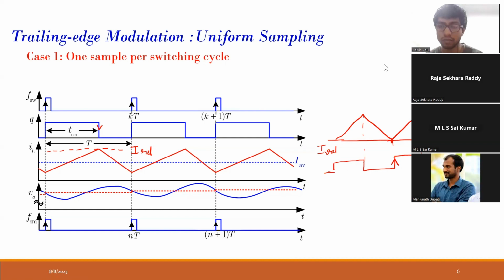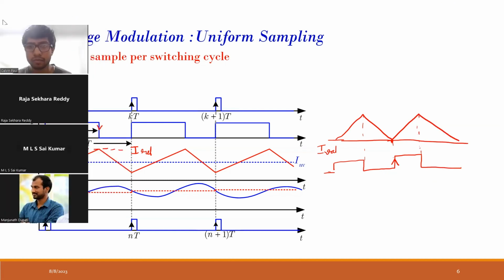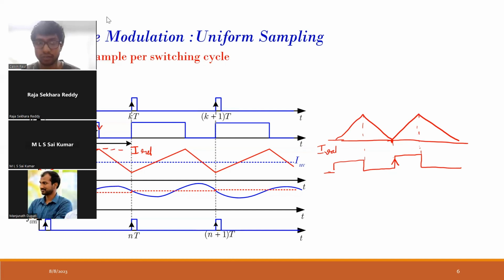Sir, in the valley current mode control, we have this point at which the gate has to be on, we are giving a trigger. But the maximum value, if the inductor current reaches the peak value, then the circuit automatically takes care of it. That is a protection feature.